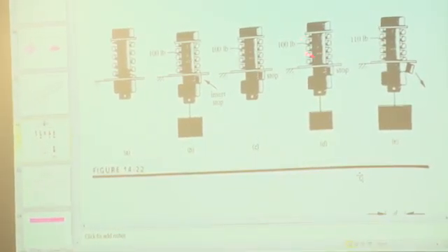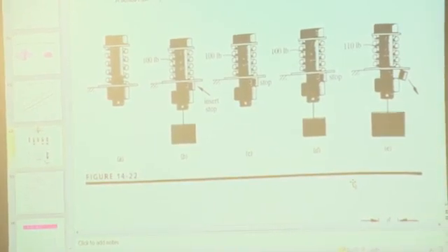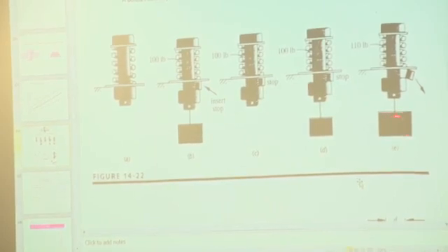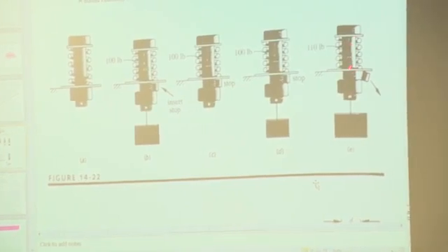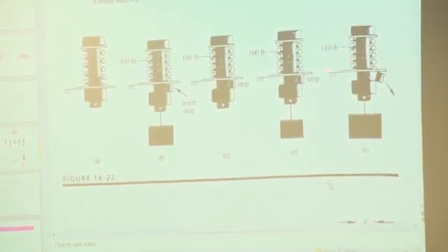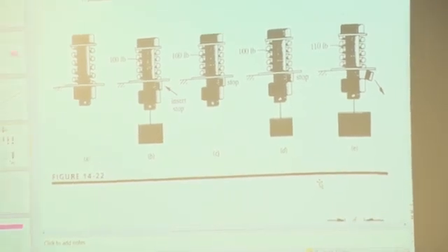Because remember that when we did this bolt, this spring here shows no change. So not all of the force goes into the bolt. If, however, I hang a 110-pound load from here, well, then that stop comes out, and now all of that force is going into the bolt. Remember that the force in the bolt here is 100 pounds, even though I've hung that 50 pound from it. So none of that 50 pound went into the bolt. Where did it go?